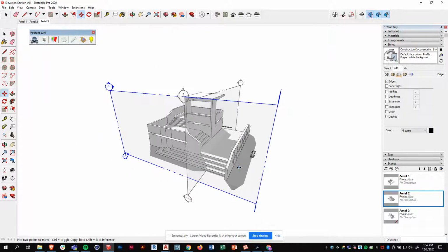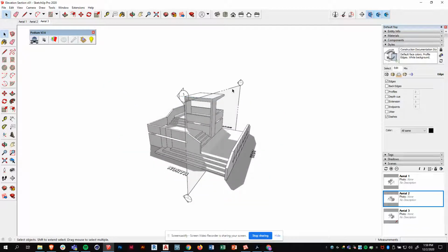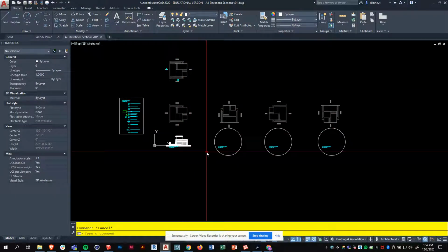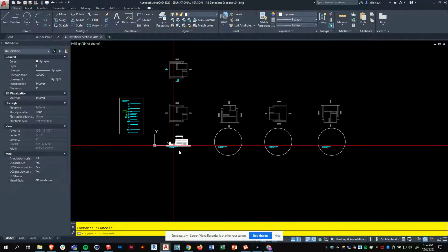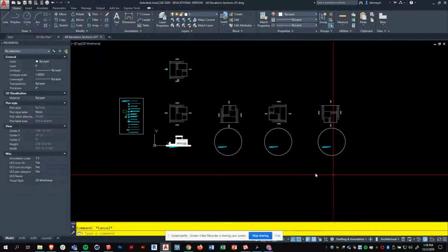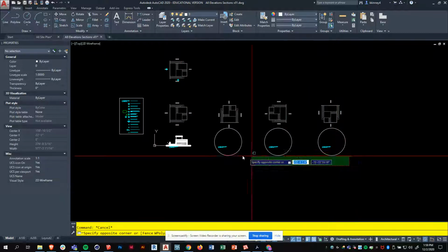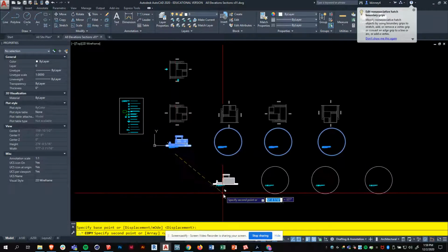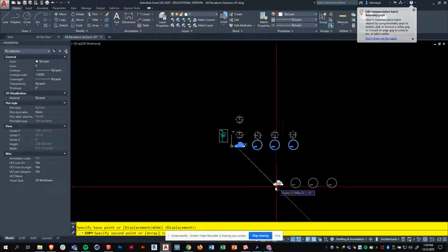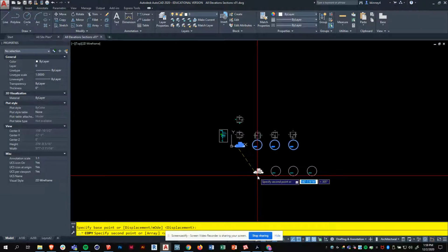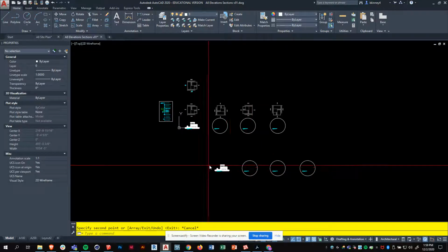But the main thing I want to explain to you is, how do we draw one of these just from, say, elevation drawings? Now, I don't have three of them here, but I have one of them, and a site plan that we already have. So to start this, I'm going to make my section drawings down here. The first thing I'm going to do is copy all of my elevation drawings and bring them over, one over and down, something like this. You'll see why in a minute.